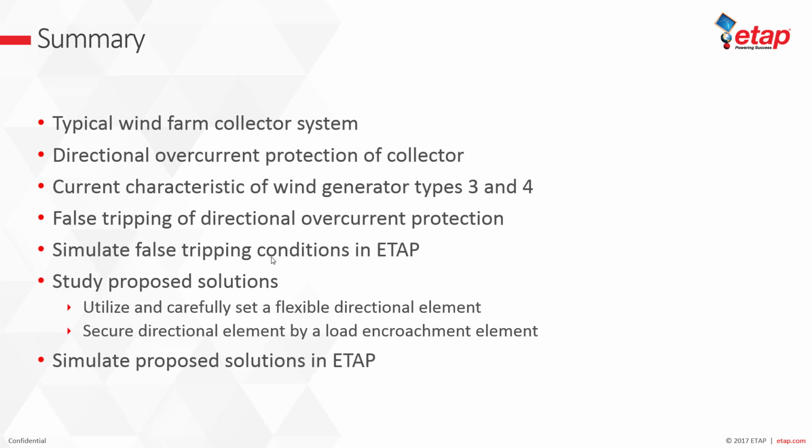Number one is when the power generated by the wind turbines is very little, less than the auxiliary power, and there is an overvoltage. For the simulated case, it was above 7%, which is a very rare condition. But the most probable case is when you have some level of active power generation, 25%, 50%, while there's an overvoltage in the system. So in that case also the false trip can happen.